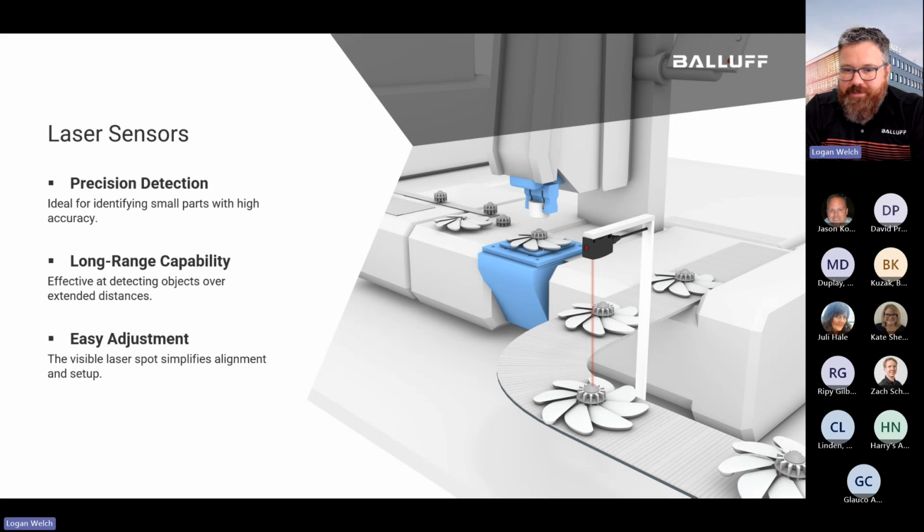Maybe you just need to be in front of something, somewhat in the vicinity of a couple inches. A standard red light is the way to go, because it's going to give you a larger area to reflect off of because of the spreading out of that light. That light wants to cone outwards exponentially as it travels through space. But laser sensors give you a pinpoint spot to detect at long ranges. So just be aware, you want to make sure your object doesn't have any dead areas around it that could possibly give you a false trip or a non-trip.